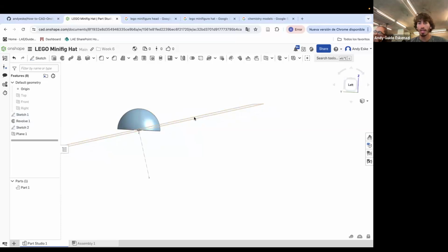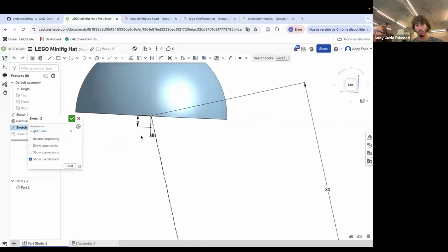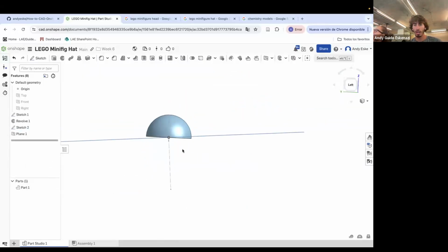And we can always edit. In fact, that seems already too high. So I can go back to sketch 2 and change that angle to be 5 degrees even. See how that looks a little bit nicer. How can you choose the dimension? Like this. D, and you click on the two lines. Let's make it 5. Perfectly. Excellent.